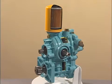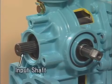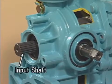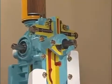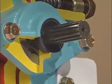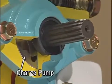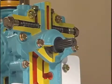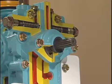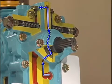Let's now look at a cutaway model to more closely examine each part of the HST and its function. As explained before, this is the input shaft, which turns continuously when the engine is running. This is the trochoid-type charge pump. The charge pump is driven by the rotating input shaft. Hydraulic oil is sucked into the charge pump through a filter in the hydraulic oil tank. The charge pump then supplies the oil to the hydraulic circuit in the HST.